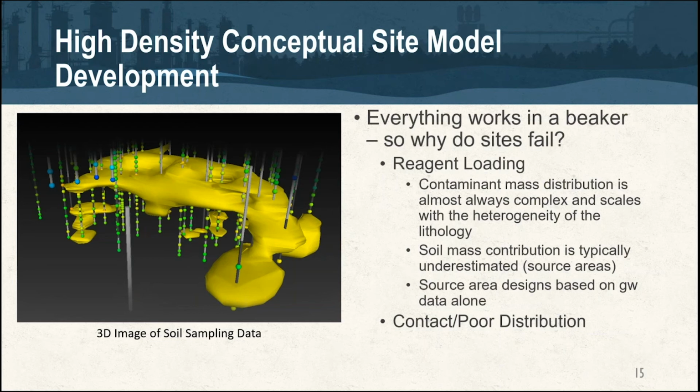I've even seen some designs that are based off of groundwater alone, which I don't think most people are doing, but some are using groundwater and running a partitioning model to back into soil concentrations. I think that's bad practice. I think you've got to have vertically profiled soil data to really understand how that mass is distributed vertically.